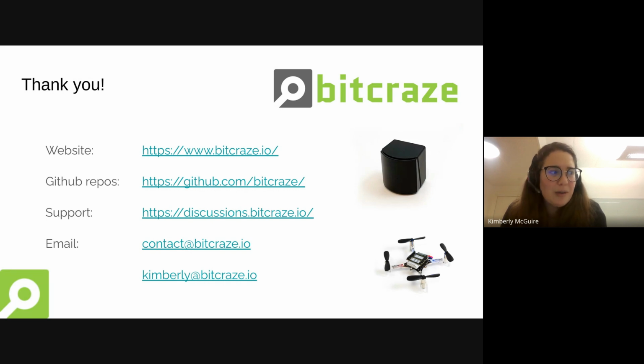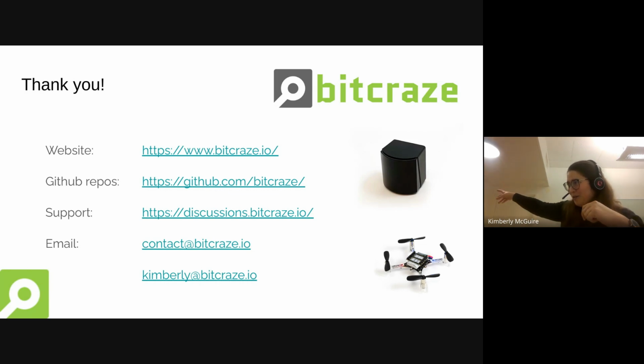A few years ago, we did a demo where we combined the Lighthouse positioning with the flow deck and even the ultra-wideband based local positioning system, where we had the Lighthouse system here, halfway on the way to the flight lab, and in the flight lab itself. There was quite a lot of space between the Lighthouse places. But the positions of the lighthouses also have to be synced up. So this is position 0, but the one in the flight lab needs to be at position 20 meters or something like that. That is something that needs to be synced up.